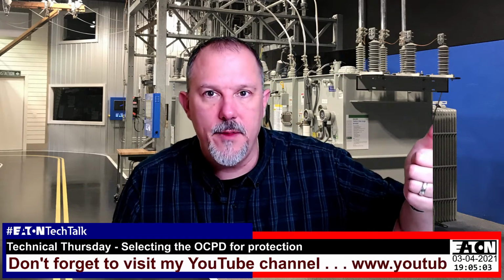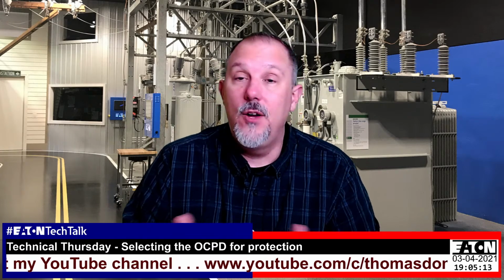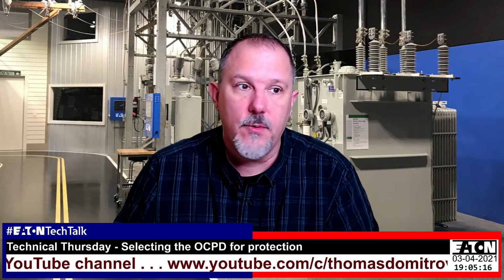Think about the success story I had with Ken White at Olin Chemical, where they were pulling conductors downstream. We had an arc reduction maintenance switch on the main that provided the clearing time all the way downstream to where they were working. And instead of like a 20 calorie event, they were left with what they calculated to be like 2 point some calories, which ended up being an even faster clearing time. And it was hard to tell where the damage was in the equipment, about the size of a dime. They were able to re-energize very quickly. And after a quick change of the pants, they were back home that evening.